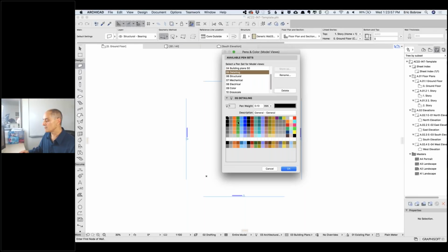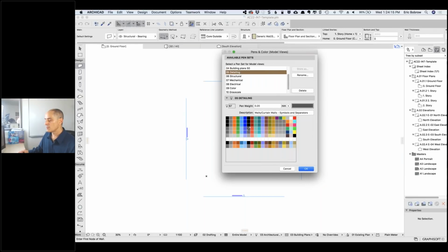Now, interestingly, if we go here, 2D elements general, cut structural, cut non-structural, etc. Where we go here, annotation, this would be walls, curtain walls general, cut structural, cut non-structural. So these designations do exist in the US version, but in the US version, only the first 2 rows have designations, just as I recall, and other ones are just colors.